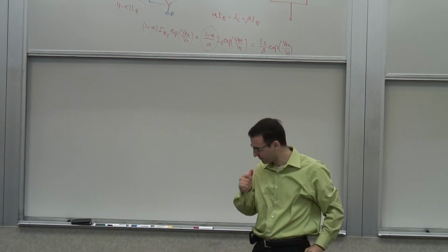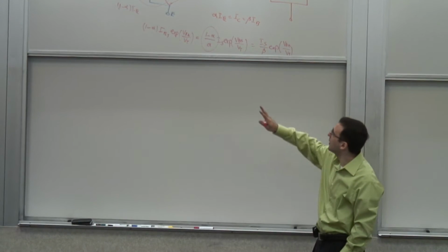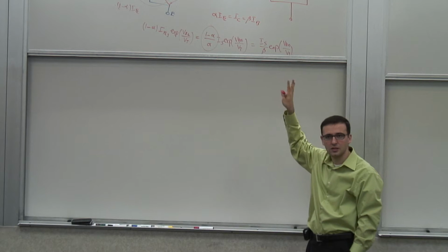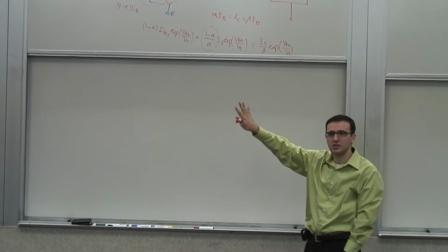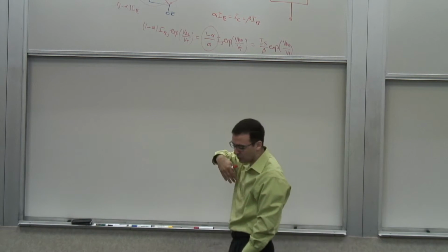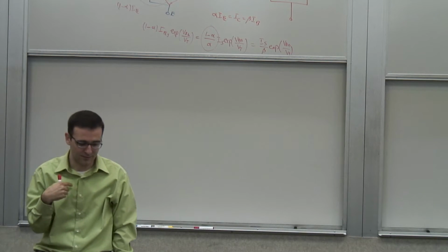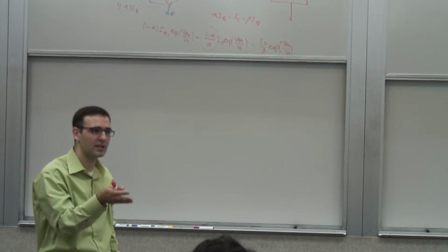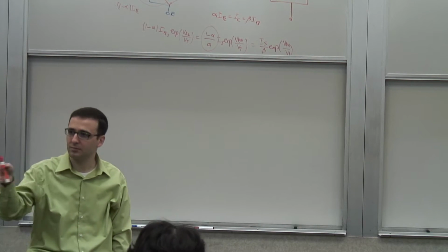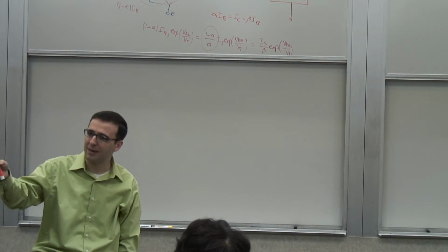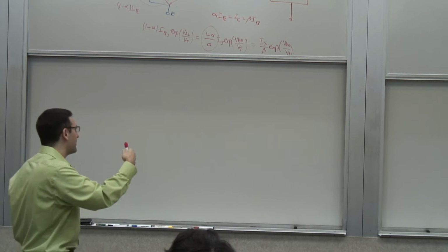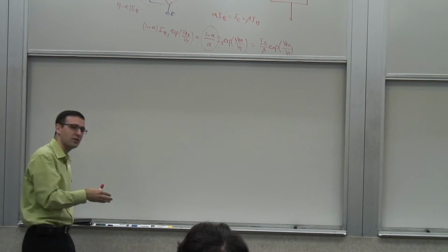Continuing our discussion. So far, we looked at the injection of electrons from the emitter side into the base, and we saw that due to the thermal movement primarily, and also facilitated by the electric field inside the base, these electrons will end up in the collector. So once they make it to the edge of the collector-base depletion region, they are in the collector.